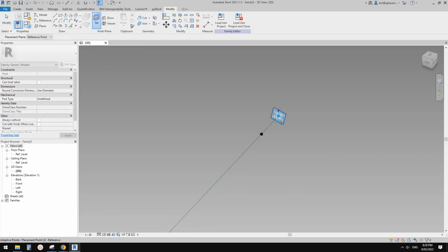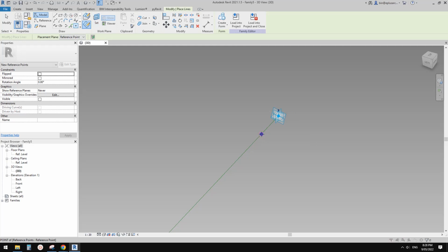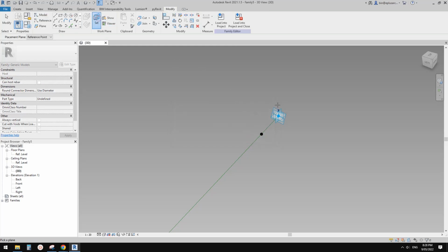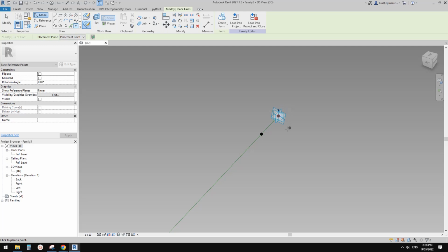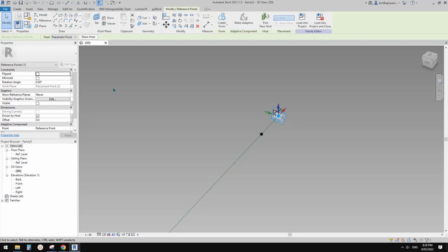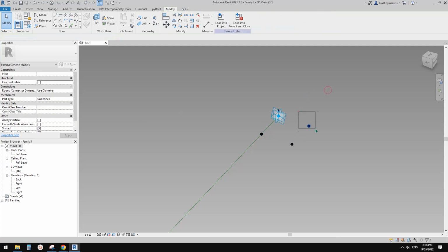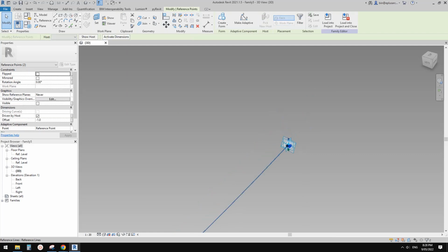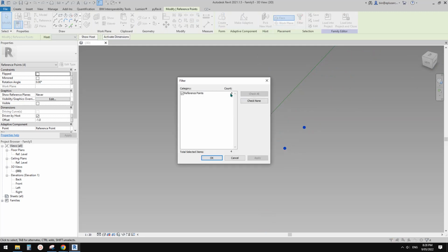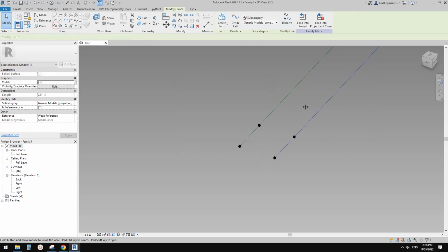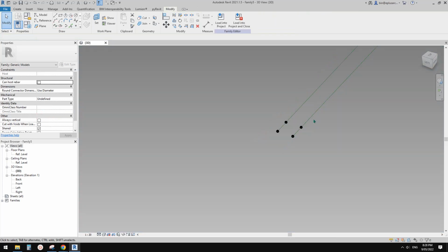Point, draw work plane, set work plane, tab, place it on here, and set work plane, pick this, place it on point 2. Select this point, -1, and select this point, same, -1. Now we can select this point and these two, 4 altogether. Create a spline and make it a reference line. Now we have another one, and then we just need one more.